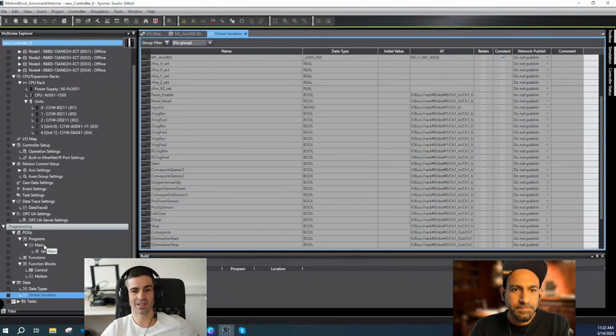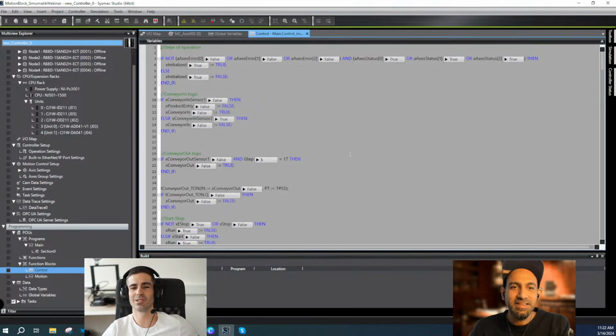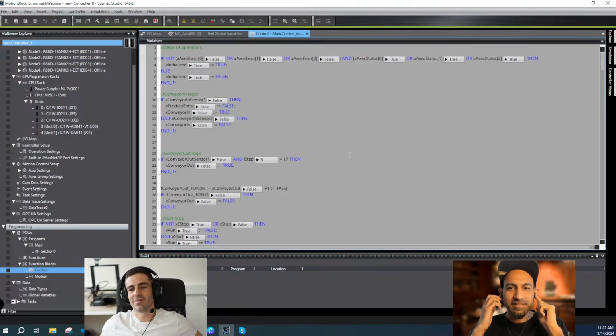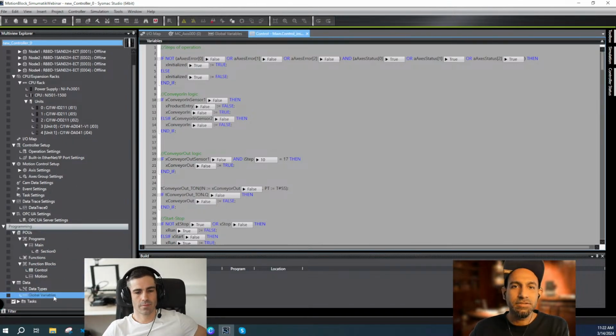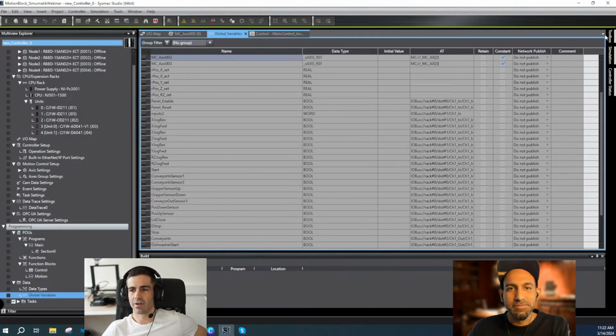The cool thing is that, thanks to the IEC standard, you did the programming in Codesys mostly in structured text. I told you probably you can copy paste the code and so on. Yeah, I did that, and you said it was pretty easy. So copy paste. This code is exactly copy paste with slight modification, and the variables I have to do manually one by one because the variable declaration here is not in ST. You have to do it like in a table. You don't have another view here. Yeah. I didn't find it.